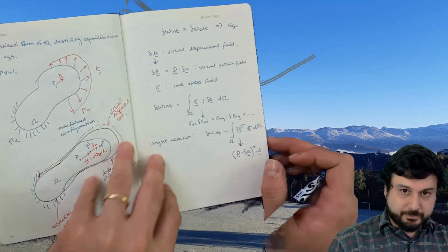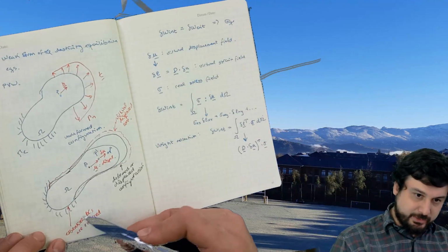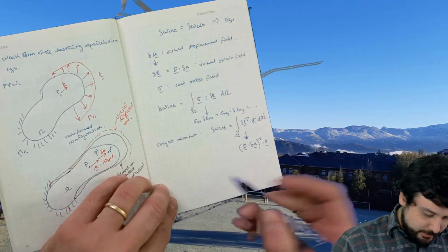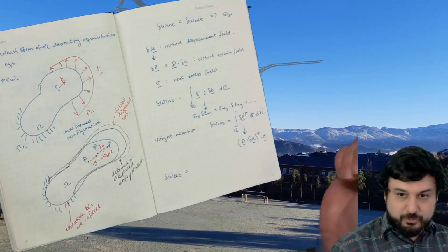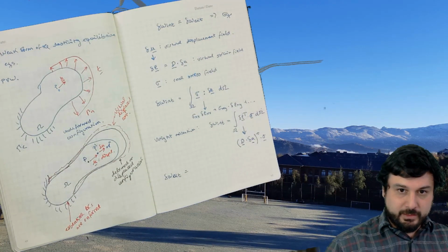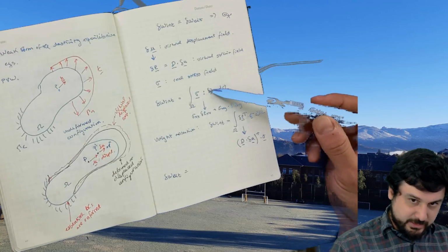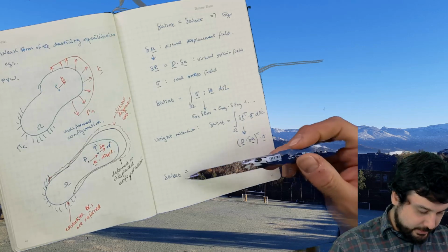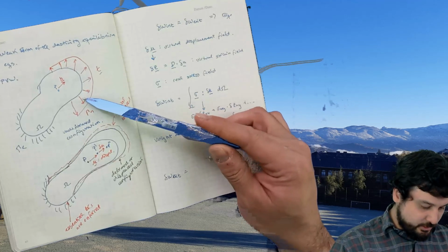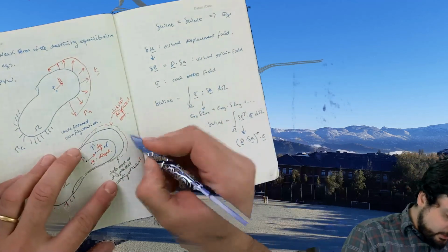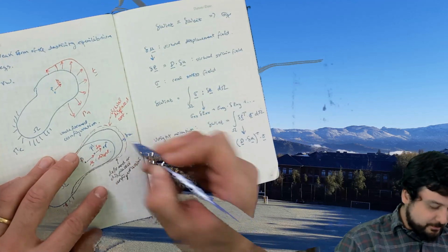Now the other side. Here's why it's important that the essential boundary conditions be enforced, because now we're going to compute the external work. Work is force times displacement. In the case of internal work, the forces are the stresses, and we're using as displacement the strain field. In the case of the external forces, we have the tractions. These tractions are going to do virtual work with whatever the virtual displacement field is at the boundary.